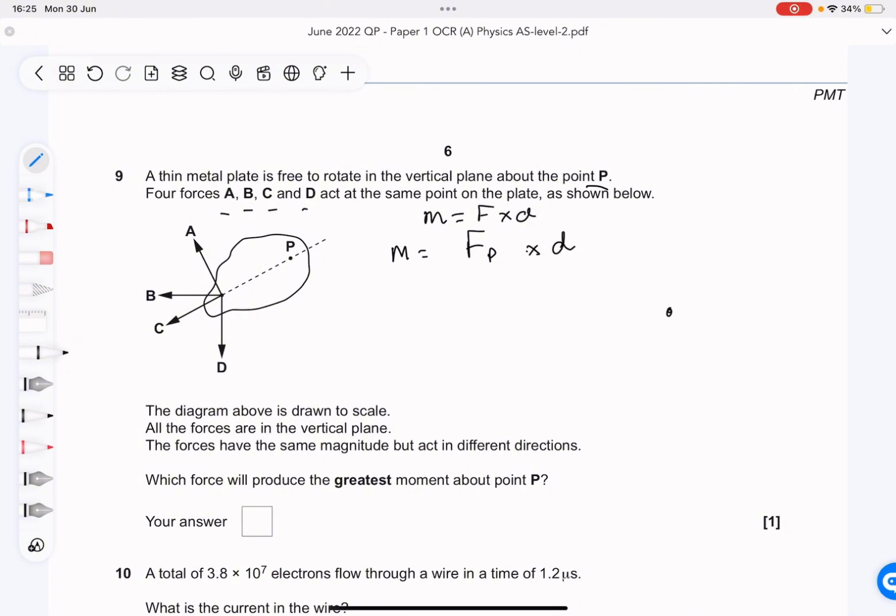So if I have a pivot here, imagine I have a beam. The force, let's say I have a force going like that, right? Now, if I want to measure the moment due to this force here, I'm not going to take the value of the force. Let's call it x, right? And let's say this is an angle of theta. I can't just do x times the distance from the pivot. I have to do x sine theta times by the distance from the pivot, because the moment is the distance times by the perpendicular component of the force.